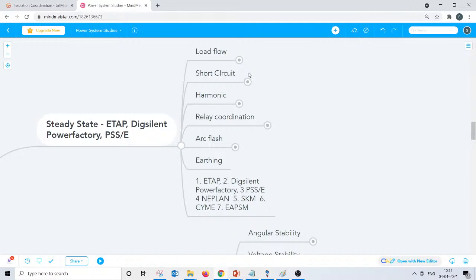If you're selecting a transformer impedance as, for example, 8% or 9%, what's the voltage drop, what's the losses, whether it's okay or not for the voltage regulation, all these things have to be identified in load flow. Combined with load flow, short circuit and motor starting, you can identify or optimize the transformer impedance. The transformer impedance you have selected should not have large voltage drops and heavy losses during a load flow or during normal operating conditions.